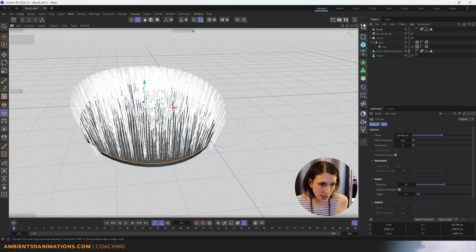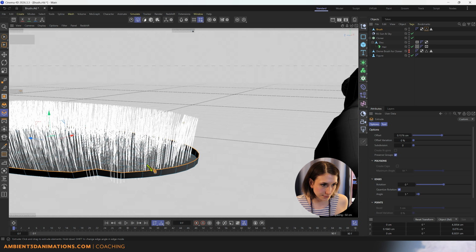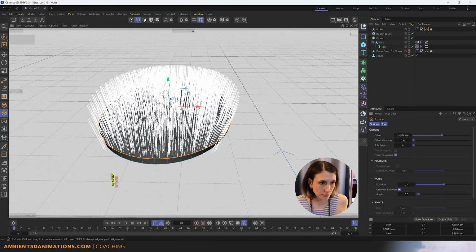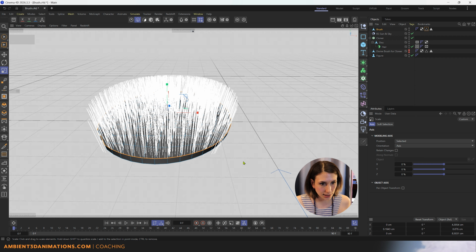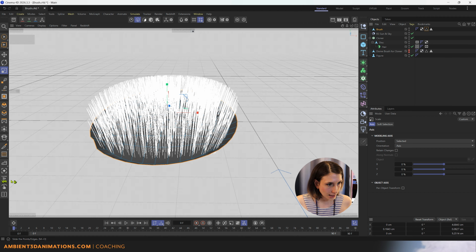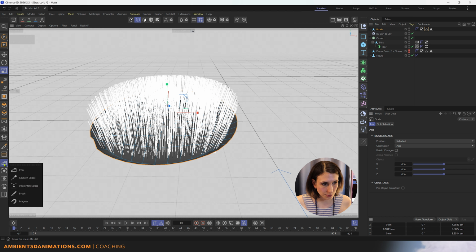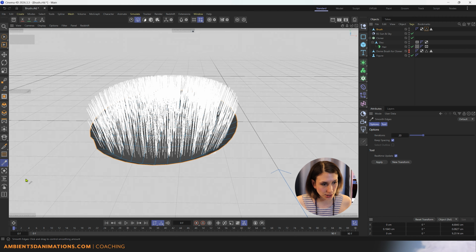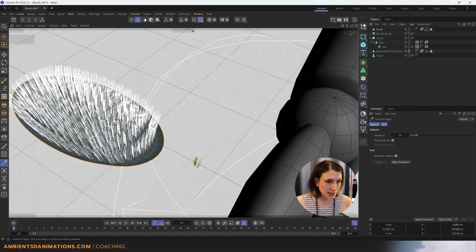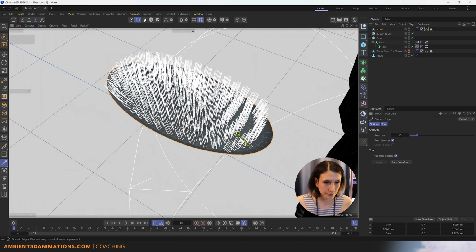If I click and drag, you'll see we are in fact making a new surface. And I can use the T hotkey in order to scale that out. And I can even smooth the edges a little bit. There's a tool within here. If you hold to click on the icon called Smooth Edges, you can click and drag, and that'll smooth out those edges in there just to make sure that that's looking smooth.